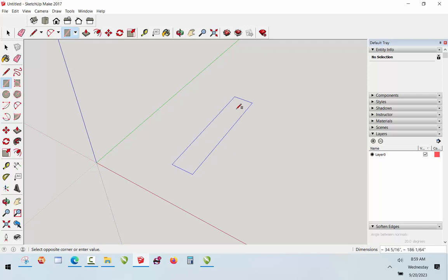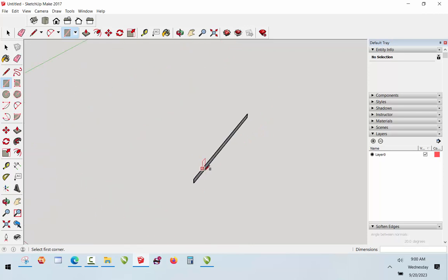Okay, so when we're working in the 3D world, we have an X, Y, and Z plane, which you probably don't care about. But basically, we're going to begin building these components of our sofa table. So I'm going to switch to the right plane. So now I'm in the right plane. I know I need a piece of wood that is 48 inches long and 2.5 inches wide. So I'll go ahead and type that in, and there's my little stick of lumber here.